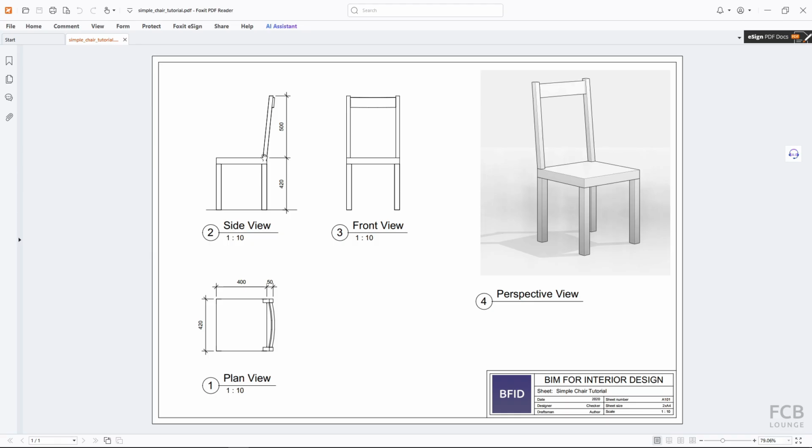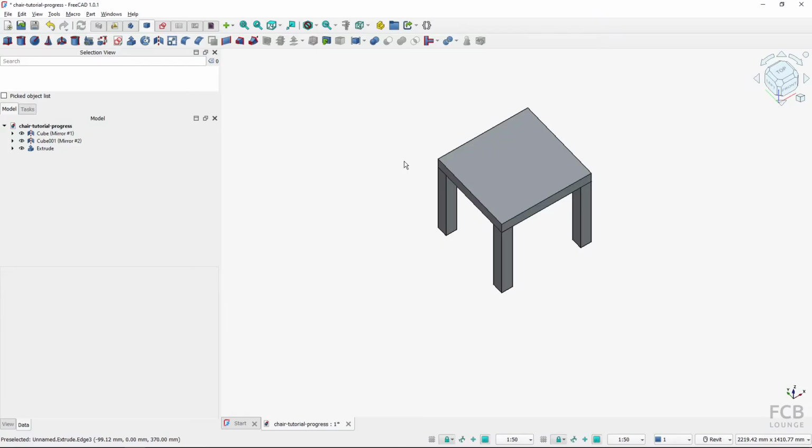We will create this object by creating a sketch, which is located here at the bottom, and then another sketch, a profile, which is placed here, and it will be placed 50 millimeters to the back, and then we will link the sketches with a Loft tool, which will create a solid again. So first I want to create the first sketch and I want it to be placed on the top of this plane.